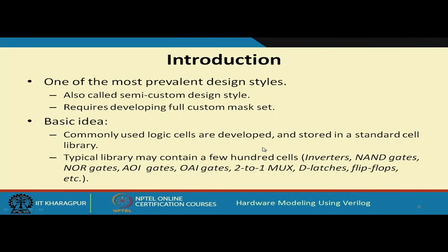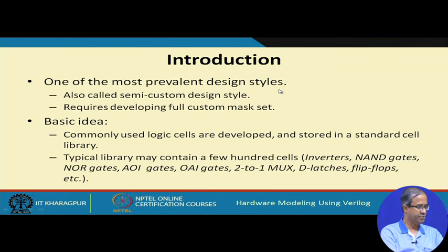This is one of the most widely used design styles for manufacturing ASICs today. As I said, this is also called semi custom because it is not full custom. A lot of the design cells are already pre-designed and available to us, we are reusing them.